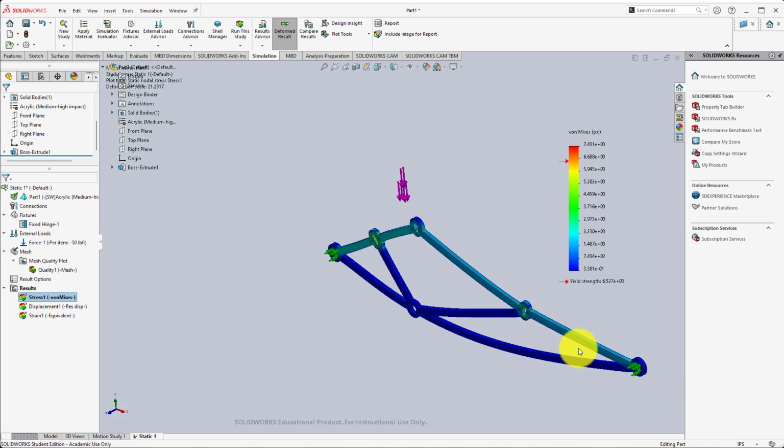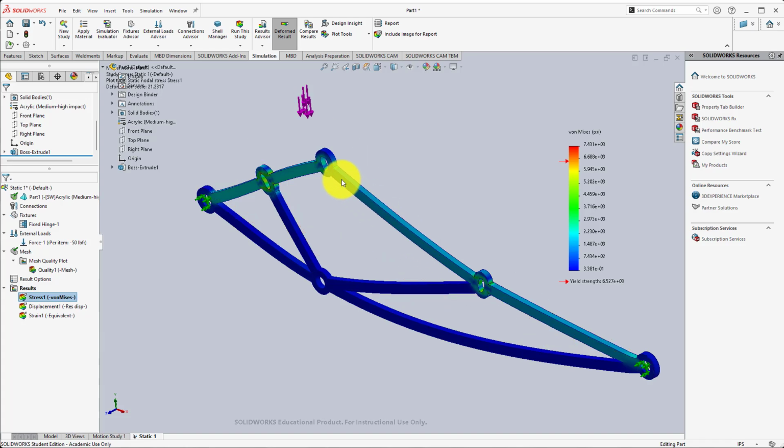Some other things I want to point out that will help you on your design, because you guys are going to have to design your own frames and figure out what kind of standard truss system you want to use, what kind of members you're going to have, and how many of these nodes I'm going to put to keep my members going from one side to the next. And you need those because you can get out of plane bending if you don't have those, and it could cause your structure to fail. And the FEA would analyze that as well.